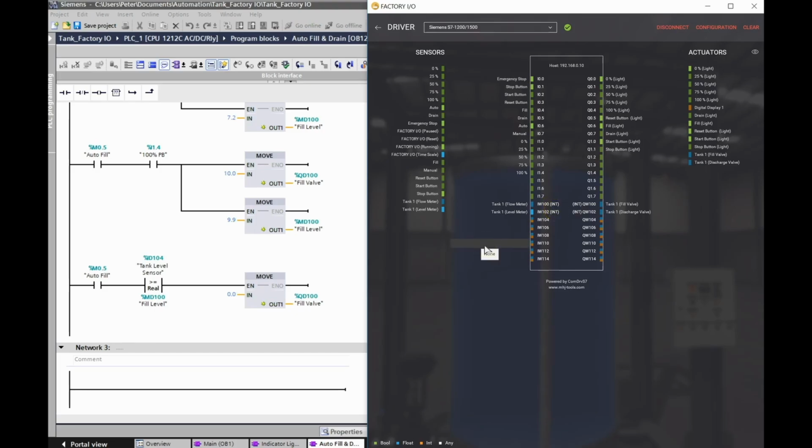So for some, that totally just maddens people because you've gotten to like the 5th video and you're like, he's been using the wrong instruction the entire time. Well, I'm making it work, but maybe there's a better way to do it. Maybe I should have changed each of these guys to an integer value, and then when using an equals expression, I would actually be able to have them equal, right? Rather than having a real value and trying to match up a value that should be an integer to a real value.